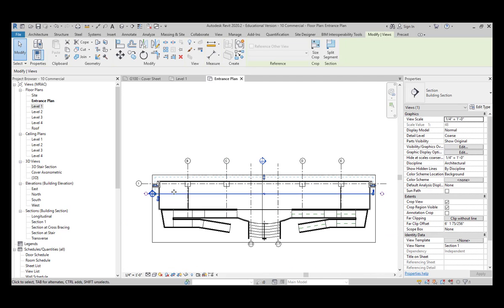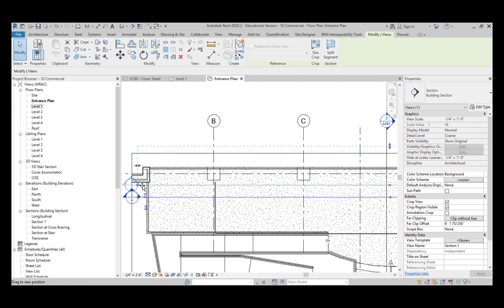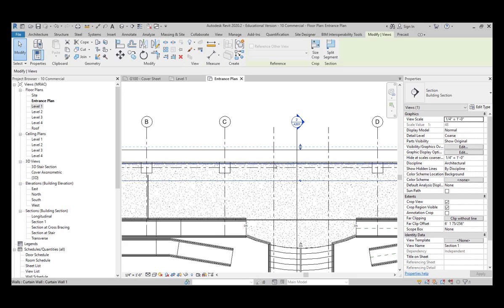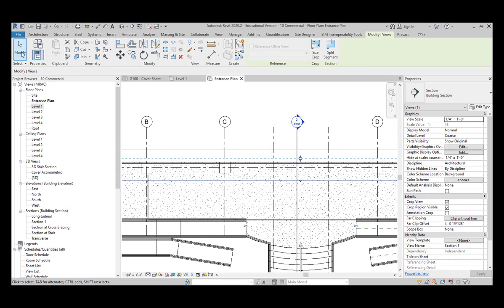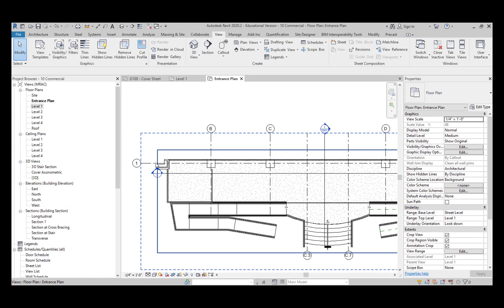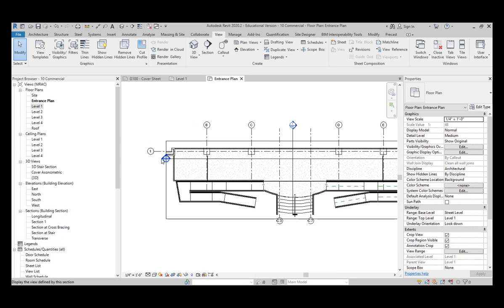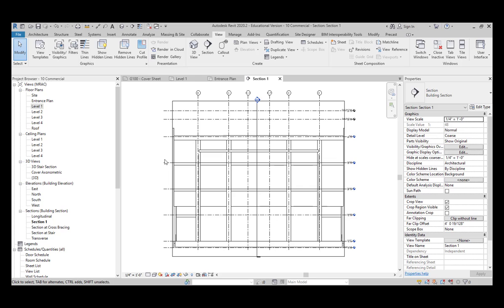And so I'm going to move this up even so that I don't have any other pieces in my way. I'm going to pull this down so that it's really just framing that curtain wall pretty much as snugly as possible. I want to make sure I can see the corner of the brick and then the curtain wall, and that's it. Okay, now when I open that section, watch what's going to happen. It's going to show me the whole height of the building. Well, again, I only need to see the first level.